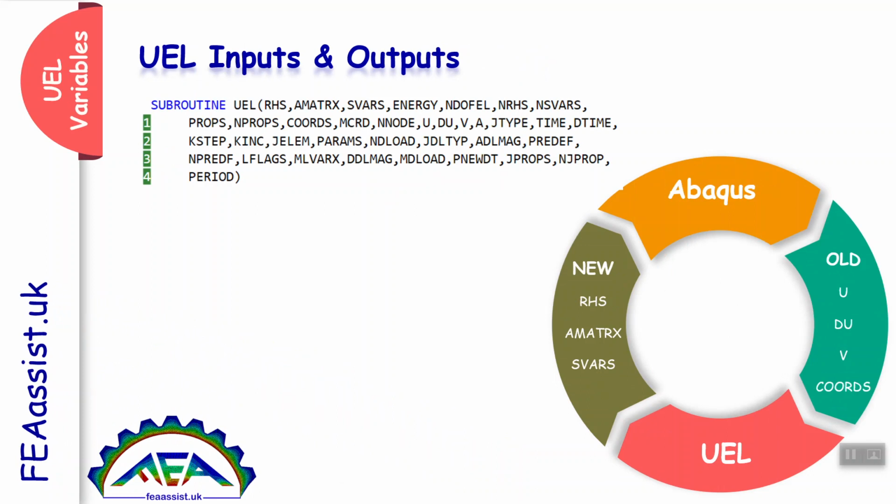Again, Abaqus gets these variables and computes the U, du, v curves. This is how Abaqus and UEL interact with each other, which is necessary to understand well to write well-working UEL subroutines.